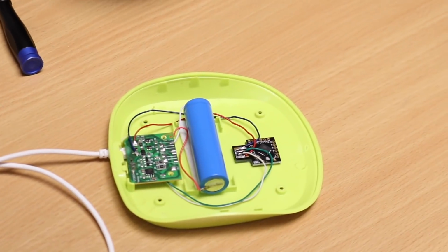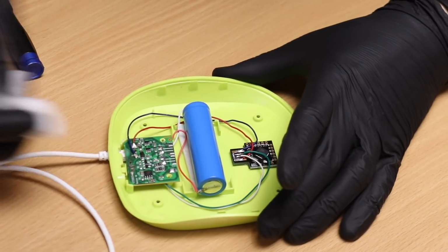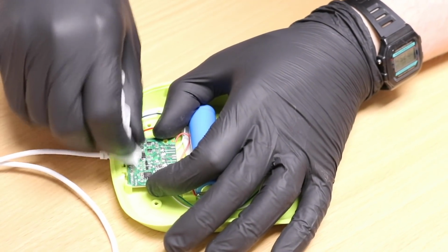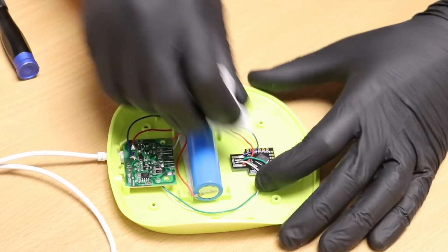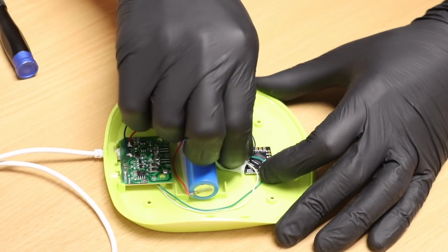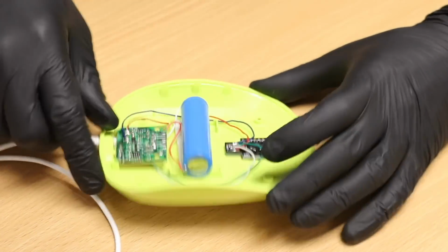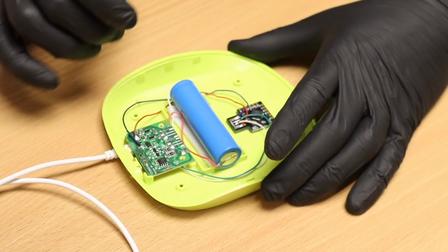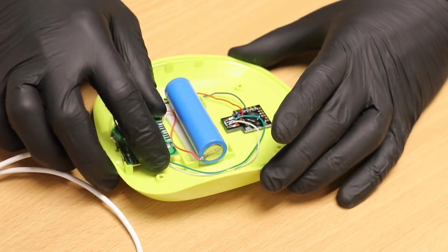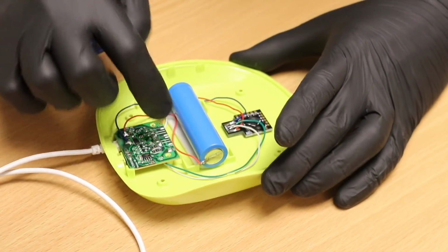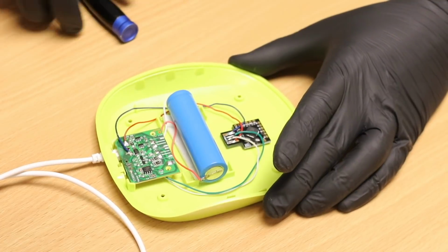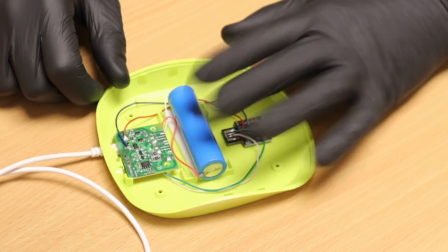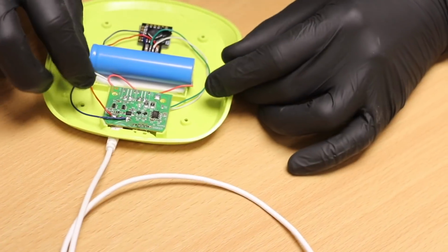Okay, so now that we've finished soldering the connections, we should clean the flux off the board. Flux that's left on the board can cause corrosion and all kinds of issues that we don't want to deal with. Alright, looks good. Next up, we're gonna secure the board, we can either re-weld these plastic pins or we can use some hot glue, and then we're gonna attach the main LED back onto it and reconnect the battery.